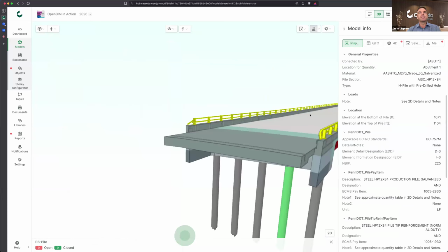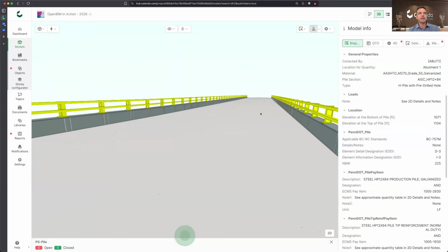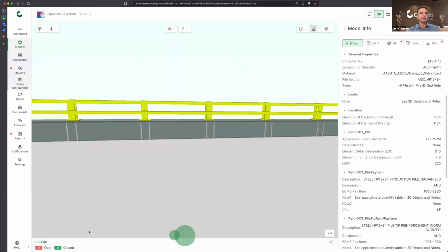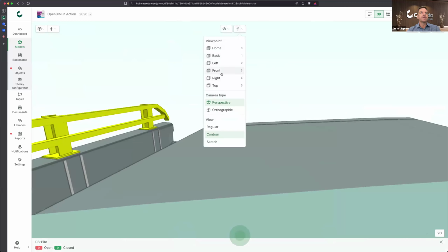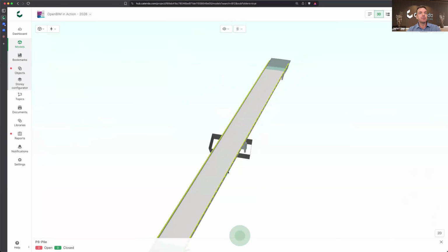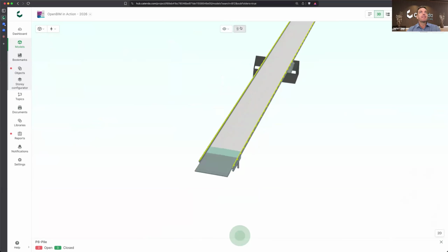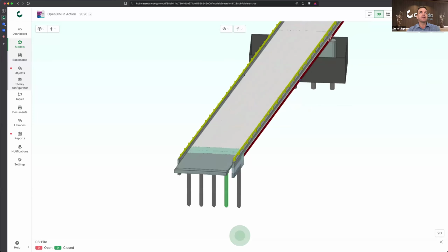It's also probably familiar from other review software. You can position your camera. If you want to, you can use your ASDF keys to walk around, or use this little tool here. You have other abilities to change to whatever perspective you want. You can do a top-down view, have a plan-looking view. There's also, as I said, a 2D integration where you can add sheets, for instance, plan views. And then as you move around, it'll actually show you on the map. Unfortunately, there weren't any of those sheets included with the IFC set. But you can change it to orthographic if you're more familiar with that type of viewing.